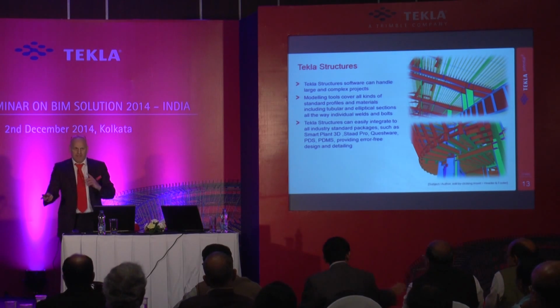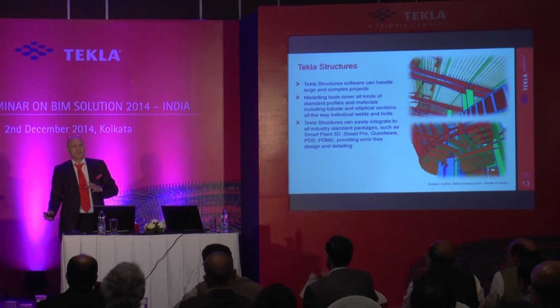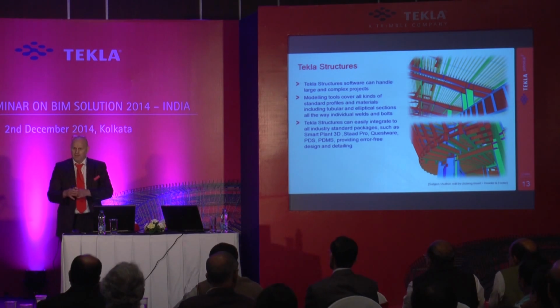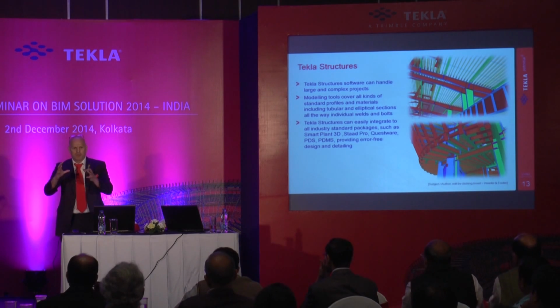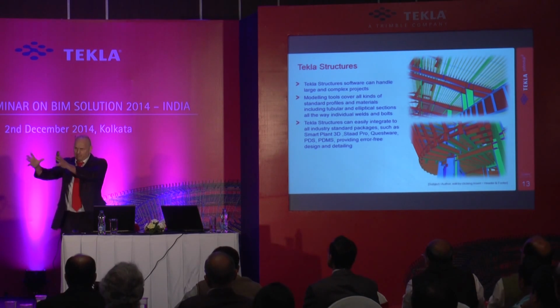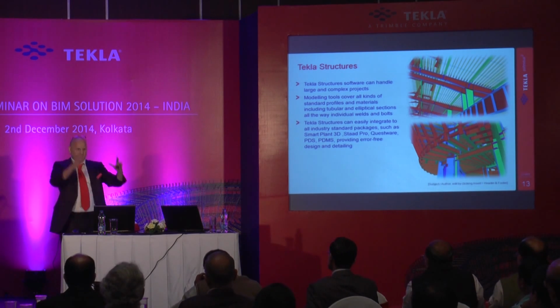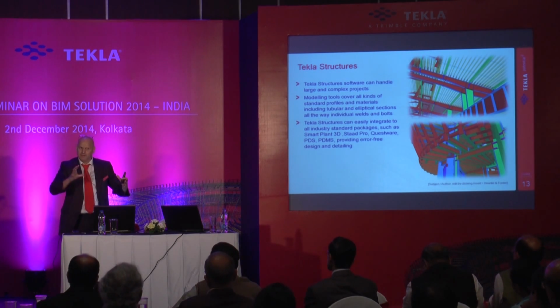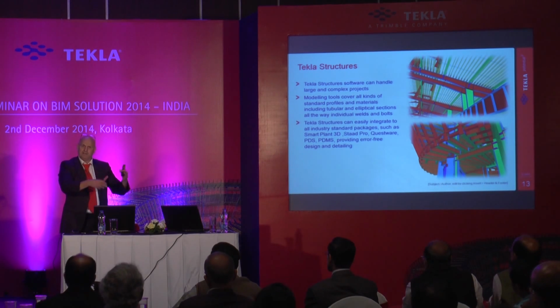And we can integrate, as we briefly touched upon earlier, if you're using analysis and design software, or if you're using a plant modeling software, you've got an engineer that's already building up a project. We can take that project from that software, put it into Tekla, and you get the 3D model based on the engineering model automatically. So you don't have to redetail it, that comes through. What that is, it's just a point-to-point model, and then we go ahead and connect it. So that's how we use that model.